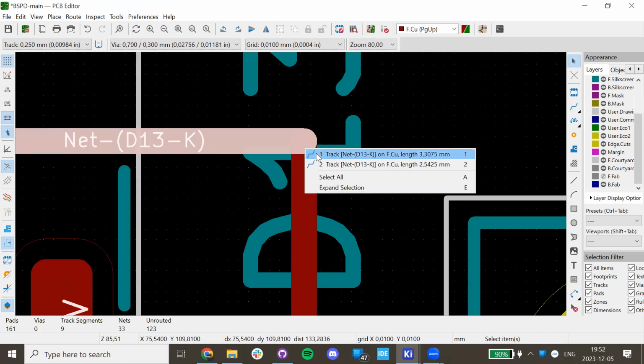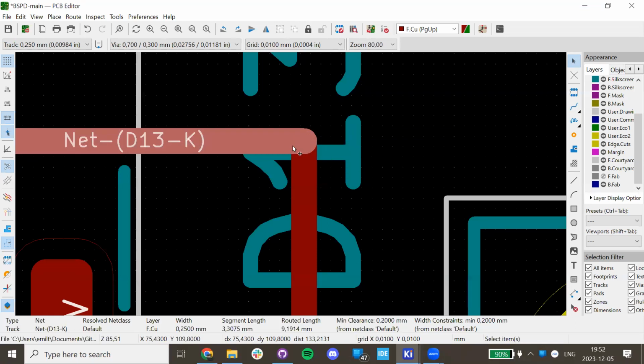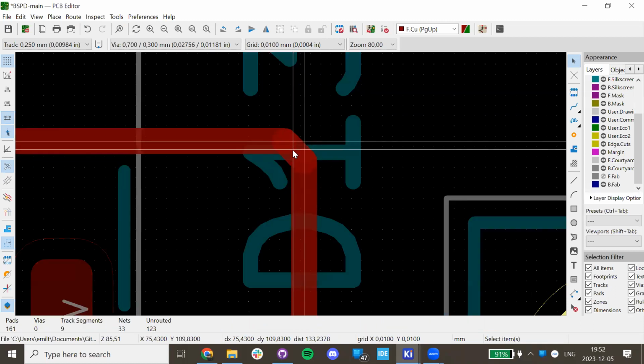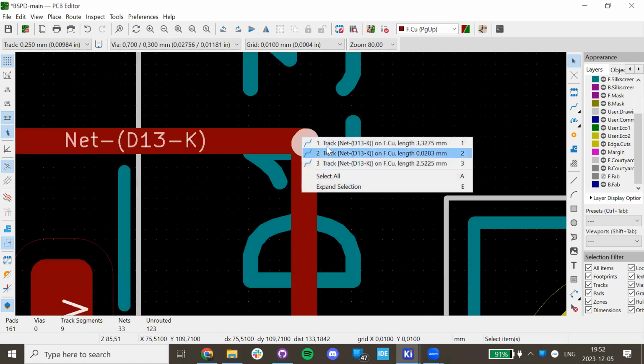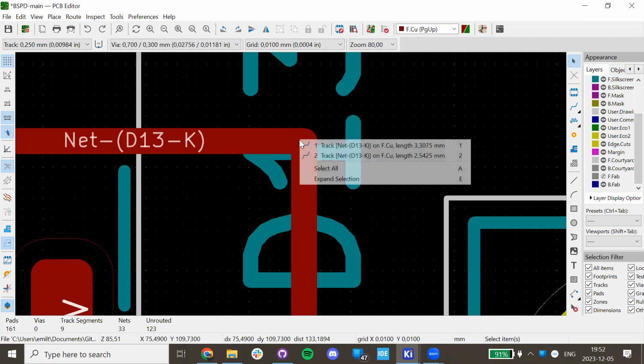And that isn't a huge deal in most signals, but all the small little rules you follow limit the noise in your circuit and the faults that may occur. And when you're routing more sensitive, more advanced stuff later, this is second nature to you. As soon as you see this 90-degree angle, you know this is not good.